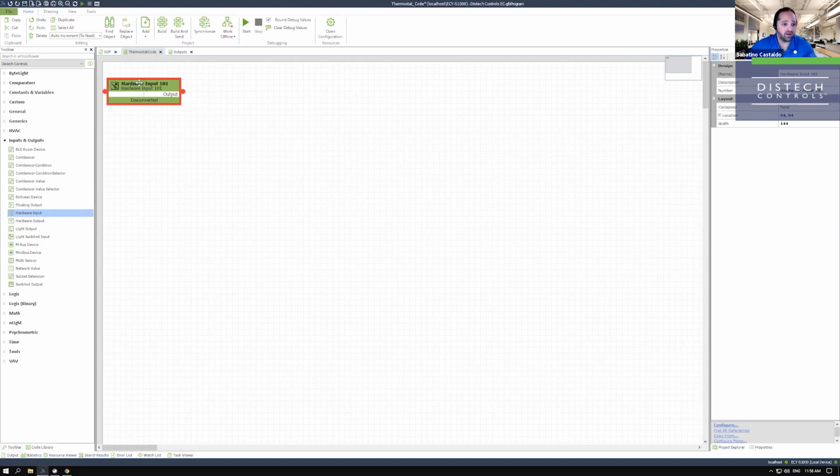So here we have the name of the object, and this is going to be the BACnet name. So when you discover it, when you create it, that's the name it'll give it. Now, what this deck has done is we've removed all illegal characters as best we could. Now, we didn't make it foolproof. You might have a character in there that's not understood, and it'll just spit it out there.